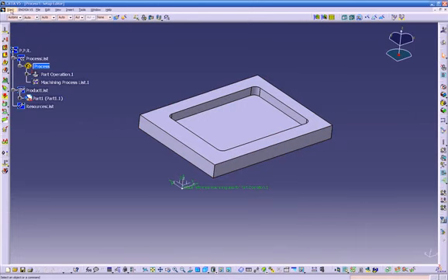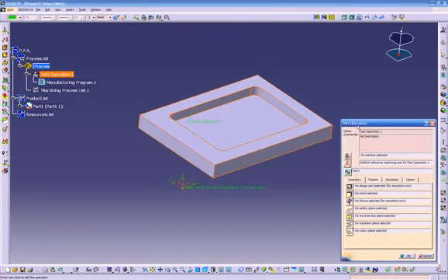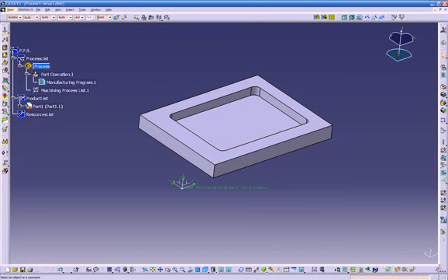Every time we start advanced machining, the very first thing we have to set up is this. First thing is we double click on part operation, and we get our part operation window. Every time we have to get familiar and used to that. We always have to do this. Before I do this, I'm gonna cancel this for a quick second because I want to create my plane and my boundary box, my stock material. So I'm just gonna cancel this for one quick second.